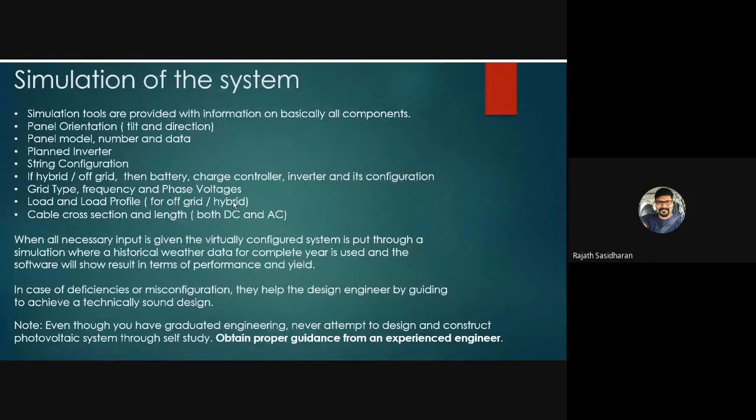Then the next is panel model, number and data, such things, and the planned inverter and string configuration, because we have combined, say, strings of 20 panels together to get around 800 volts up to 900 volts. So these are all tentative things.